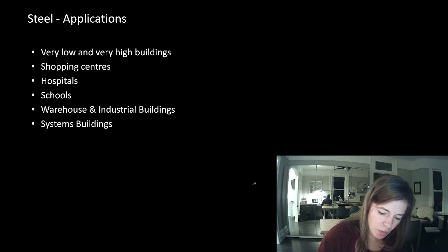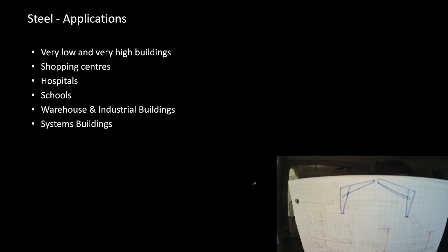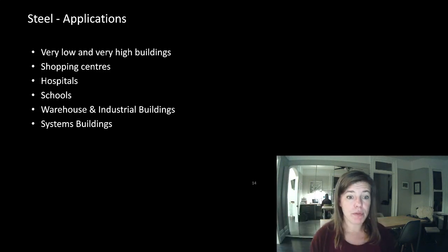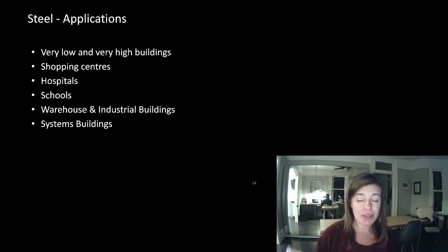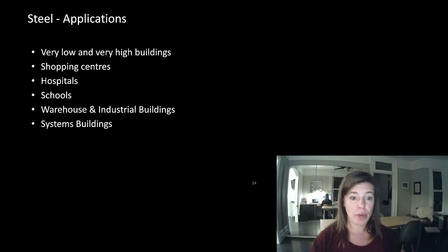I'm going to draw one here, and we're going to see pictures of them in a few minutes. So they tend to look like this. So the blue is the steel. Those would be arches that happen every few meters, probably at 8 meters, maybe 9 meters on center. And then some sort of decking or girts or wood framing going from frame to frame.